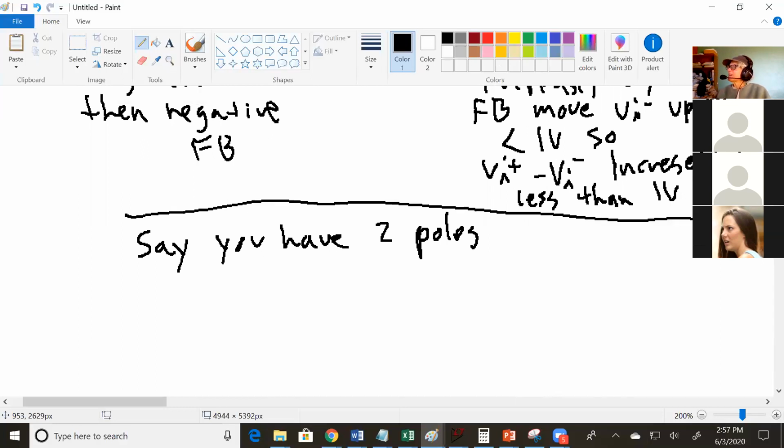So what happens is if you have 2 poles, your phase shifts 180 and the signals that were negative feedback become positive feedback. They flip. So if you had this and you flip it, now it's this. If this is negative feedback, this is going to be positive feedback. So at 2 poles, you can get in big trouble if you have your circuit hooked up with feedback, because the signal just naturally flips, and now you have positive feedback and your amplifier will fail.